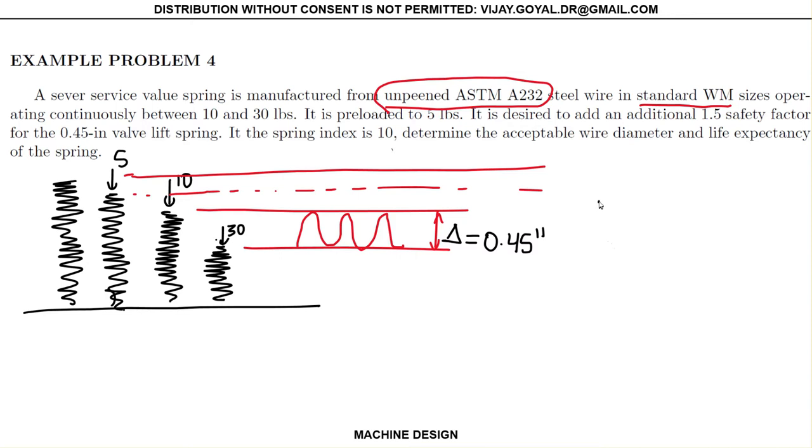And we are told we have an additional factor of 1.5. So that means I have my 1.5 multiplied by 1.2, that gives you 1.8. That's a new design factor I'll use. We don't add these up. We don't replace this with the old 1.2. This is a standard value. We have to add that to our standard that was given.